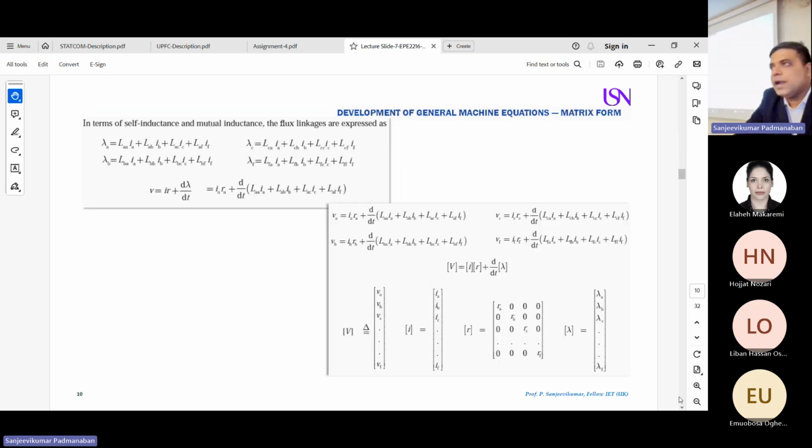Then these equations, I didn't go for derivation, it is not required. These are basics of your electrical machines, so I take only the important equations. I'm looking at the flux linkage in phase A, phase B, phase C, and this is due to the field excitation. So we have four equations for how to calculate it. You can see the formula here. This represents the inductance of phase A, this is the inductance between phase A and B, and this is the inductance between phase A and C. Subsequently, the currents in all the three phases and the field. So you can use these equations directly to model your system.